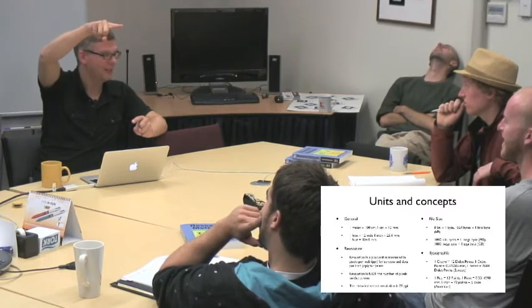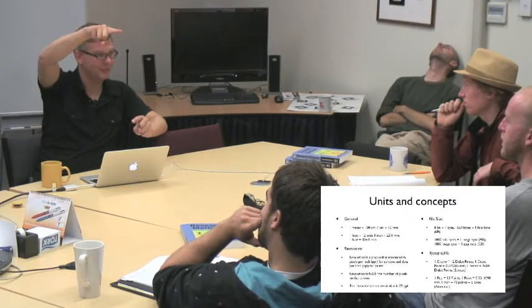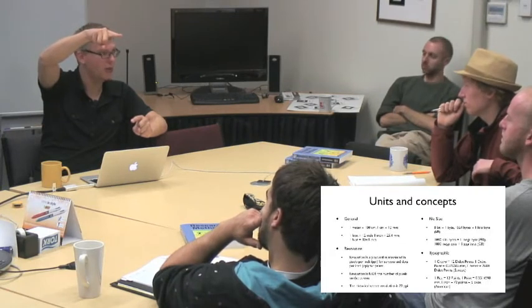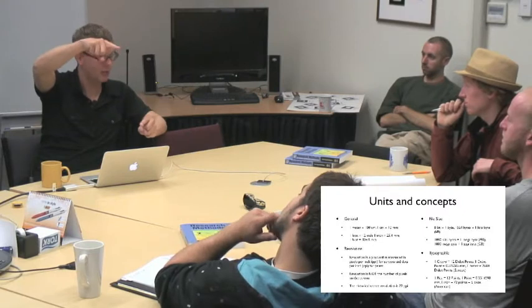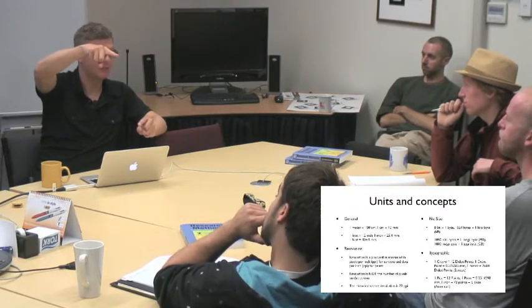No. 10 points. And a point is? 0.35. So 10 points are? 3.5 millimeters. So if you choose a 10-point typeface, then your letter will be 3.5 millimeters tall.